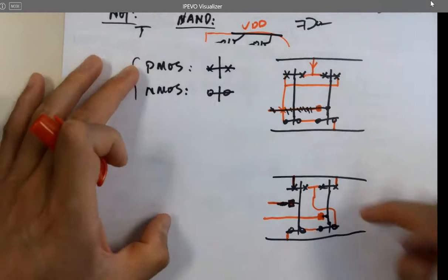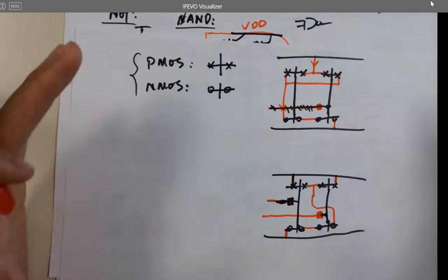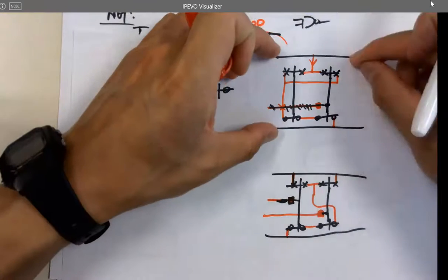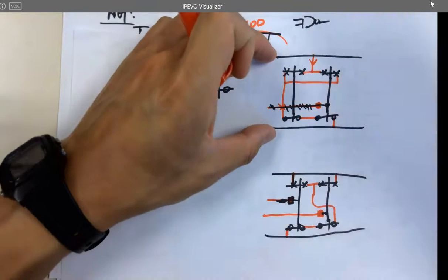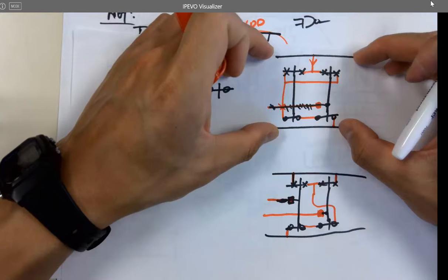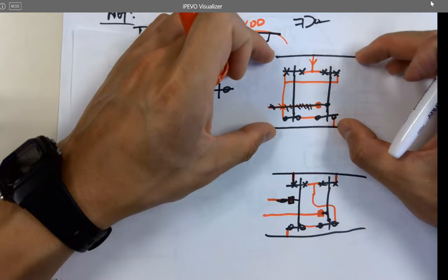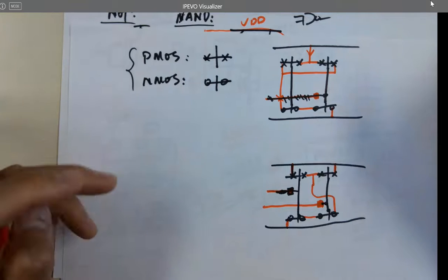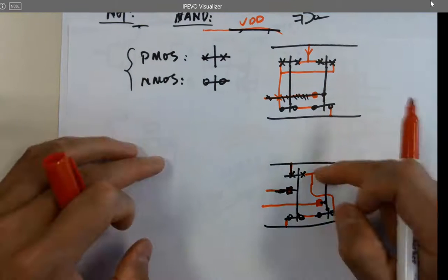Compared to this one, it's a lot better, right? Yeah. Solves the problem. You don't need to route all the wires to a lot of places. So if you route it here, then this is just one cell. You have thousands of the same cells. You're introducing more risks to short to other cells. Make sense? Still not the best.